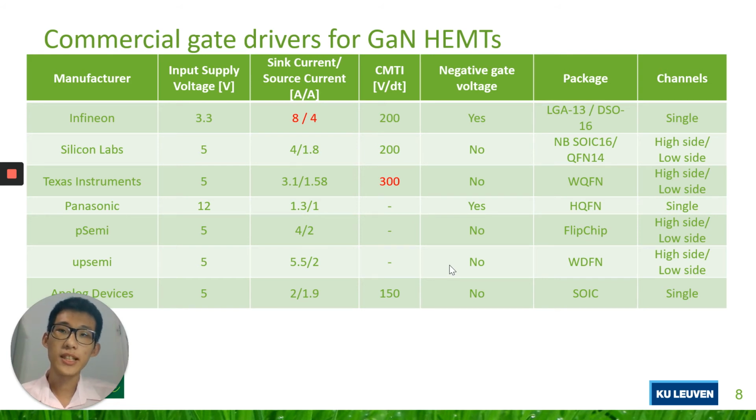Also, Infineon and Panasonic gate drivers allow negative gate voltage, as mentioned in the previous session, to prevent a spurious turn-on.